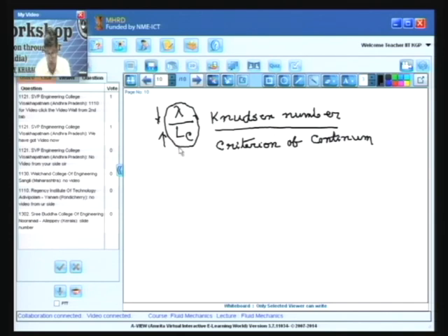That means, if the Knudsen number is high, that means the mean free path becomes high, depending upon the state of the system. For example, for gas at rarefied pressure, at very low pressure near vacuum, this lambda becomes very high, or the length becomes very low on the other hand, which Professor Suman Chakraborty told today, in the applications in microfluidics.